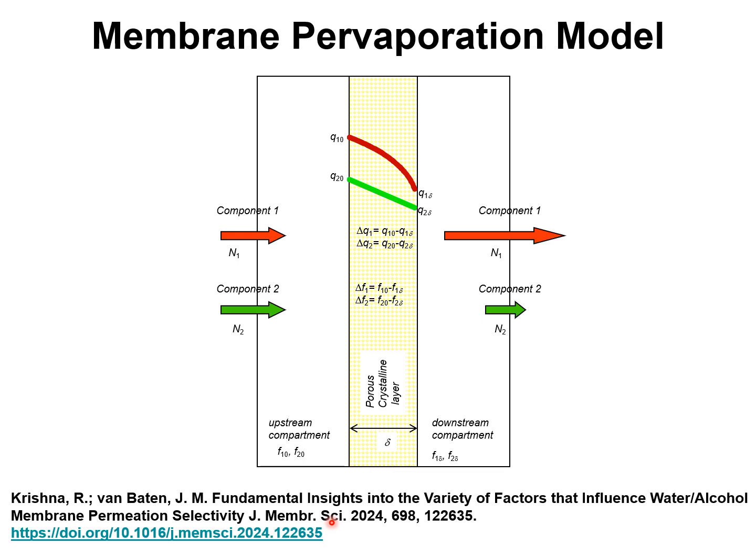The membrane pervaporation model has been applied to calculate the fluxes and permeation selectivities for water-ethanol mixtures across DDR, chabazite, and ZIF membranes.